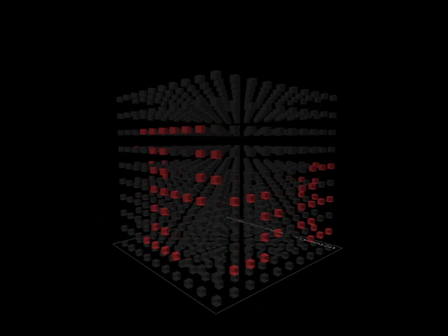The LED cube is made up of columns and layers. The cathode legs of every LED in a layer are soldered together. All the anode legs in one column are soldered together. Each of the 64 columns is connected to the controller board with a separate wire. Each column can be controlled individually. Each of the 8 layers also has a separate wire going to the controller board. Each of the layers is connected to a transistor that enables the cube to turn on and off the flow of current through each layer.